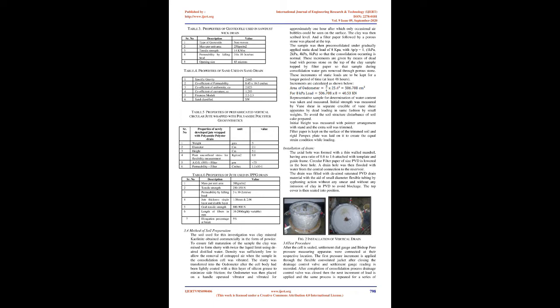3. Scope and objective. The hydraulically pressurized oedometer, Rowe type, with a central geodrain is employed in the present investigation, and the Cvr value is determined for both settlement and pore pressure readings. Measurements of pore pressures are planned to be carried out by the conventional Bishop's pore pressure setup and extensometer.